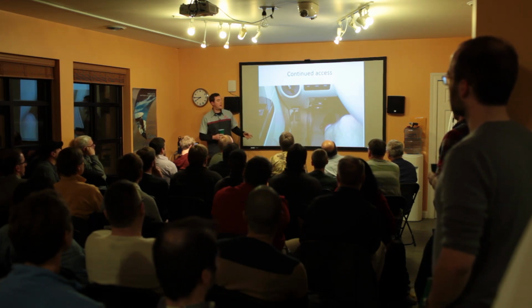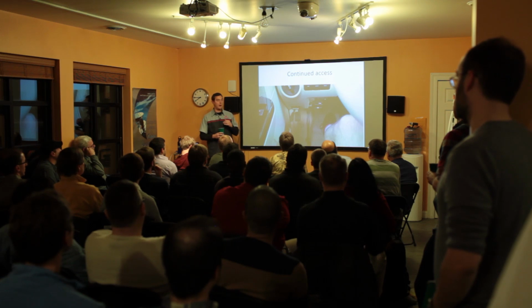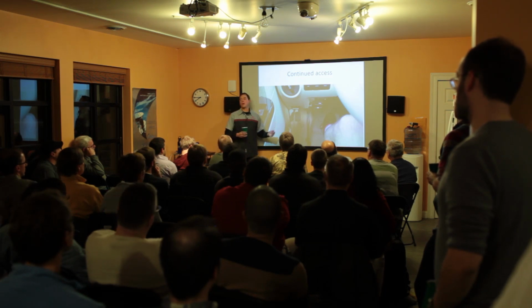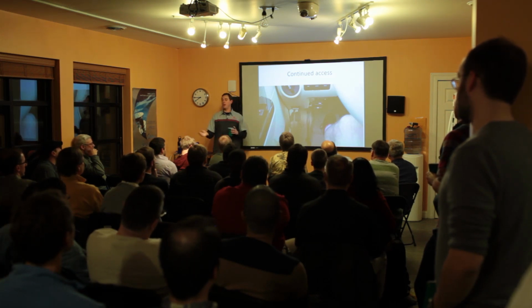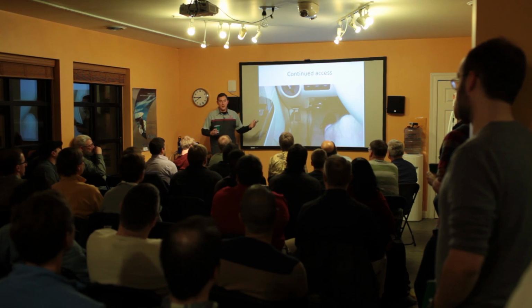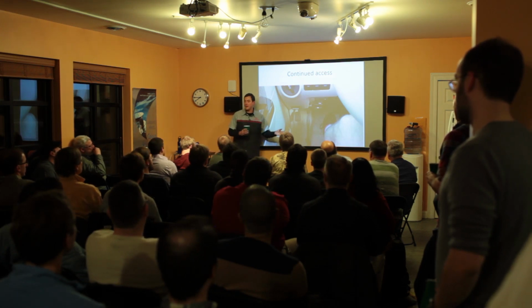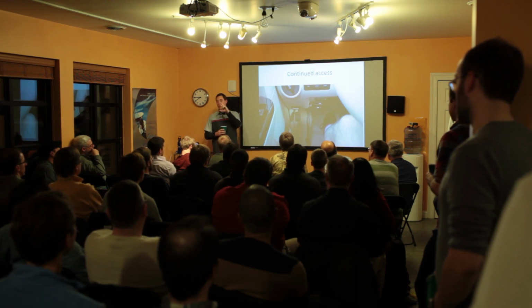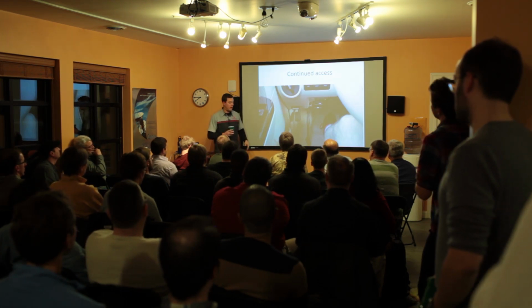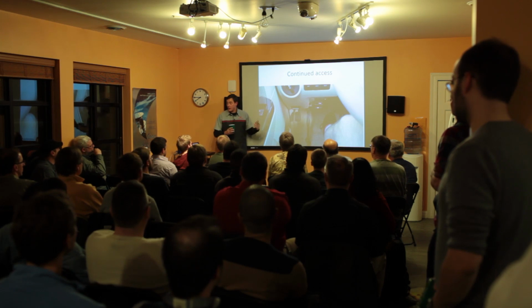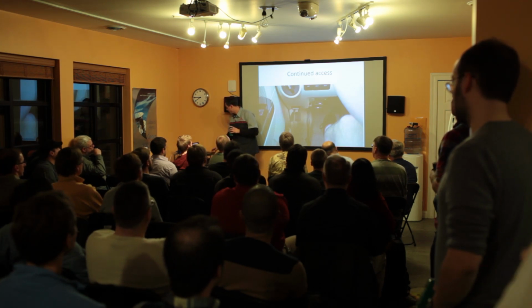We reflash some of the firmware to always think that the car is going in reverse, so the backup camera will be on. The reason we did that is because it's the most benign thing ever. The car will still function, it's not going to explode. Since this was a routine control, there's a portion of memory that we can just write to. The ECU still worked properly. We just had also our code.